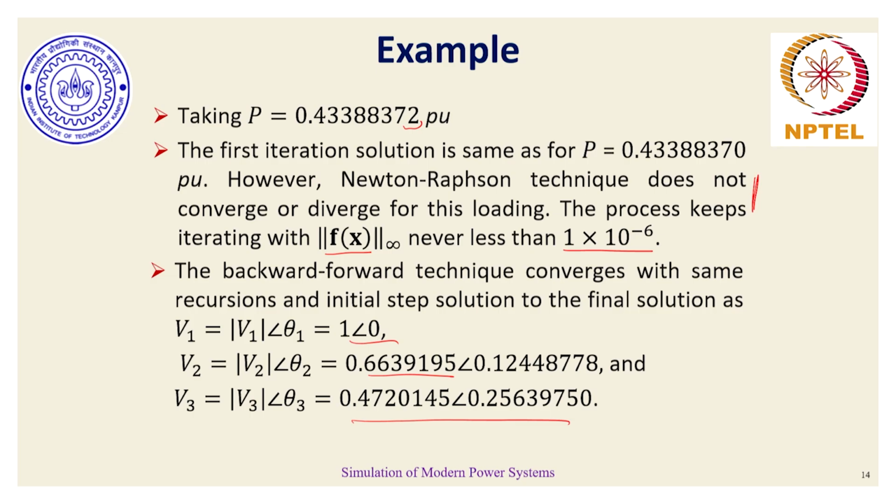This is clearly an example of how conventional transmission network power flow techniques may not work for distribution networks. In fact, what is happening at this particular load is that the radial distribution network is reaching a point closer to a voltage unstable operating condition, where voltages are so low, still the network is able to operate.